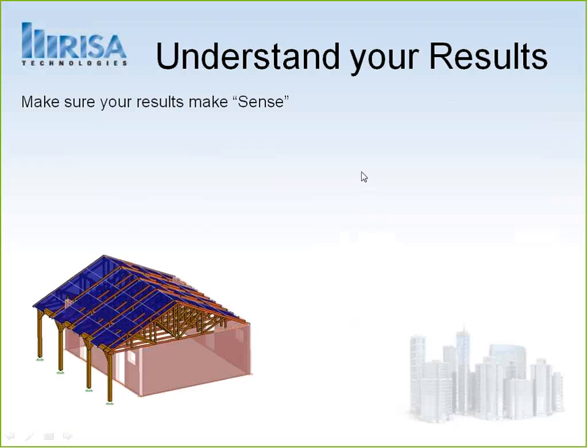So as we jump back into a model here, more of the model basis, one of the things, as we said here, check your local axes, but make sure everything makes sense in your model. So this is kind of a model I got back several months ago, and it looked like everything was okay. I see it's masonry walls, wood beams, a truss system. They have the plates on top for the roof system, and it looked okay. And the user was asking me why the results just didn't seem right, and he had a sense of it just didn't make sense.